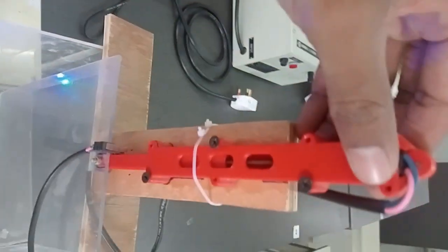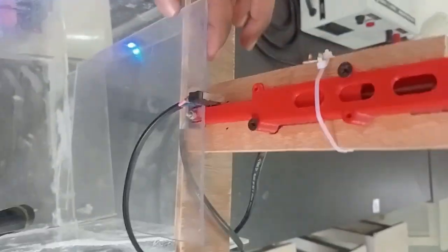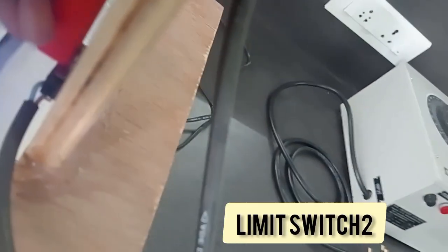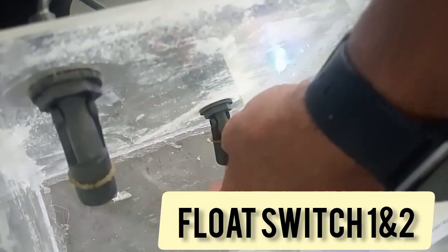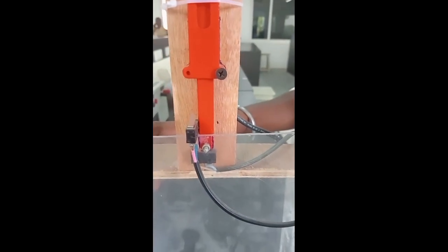This is the prototype of the dam system, and this is a linear actuator. This is limit switch 1, and limit switch 2 is available here. You can see float switches 1 and 2, placed inside the dam setup. The power supply is given to the Delta PLC, which receives signals from the float switches and the limit switches, and also sends a signal to the linear actuator.